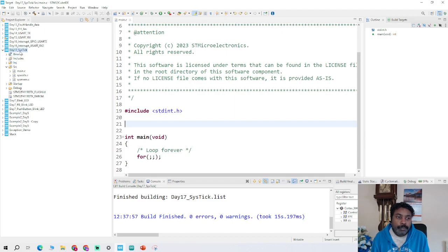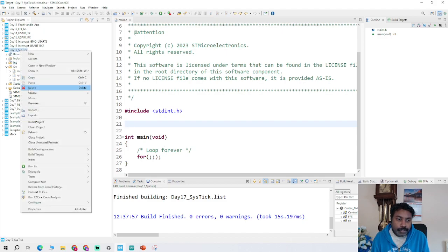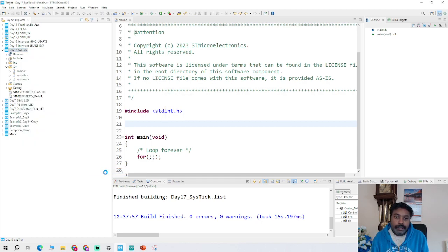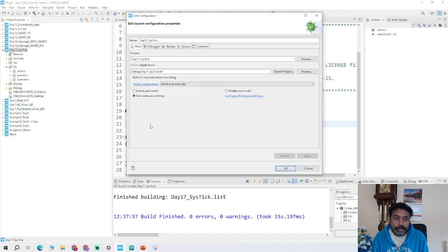Before writing, you can set your debug options, because the STM32F411 has a built-in programmer to debug. By going to STM32, it chooses the .elf file by default, but if you want to use the debug configuration, you have to set it. I'll go directly here because we built the project and therefore the .elf file is generated, so it's already linked. We skipped one step basically. Otherwise you've got to go and look for it, which you have seen in the previous sessions.